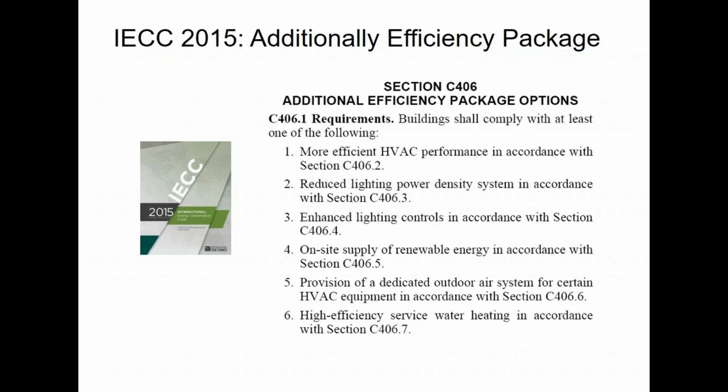That's not a thing. So if you're doing a rooftop project and your architect or designer wants you to go down path number 1 here, you need to either push back and say we can't do it, or you need to say we're going to do it for you, but now it's going to be a chiller job and not a DX job. At least not a DX rooftop job. Right? It could be a DX air handler with a boiler. You could do it that way, I guess. So I point that out.